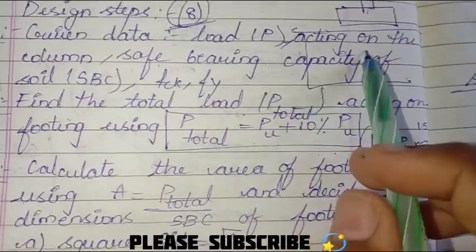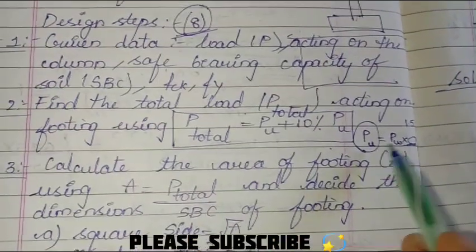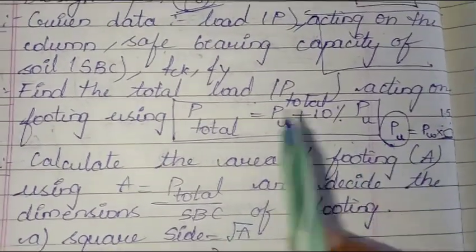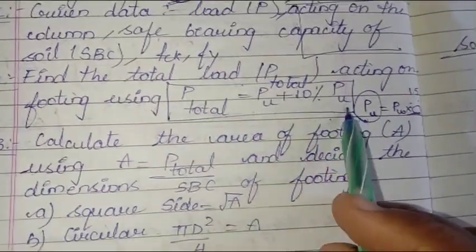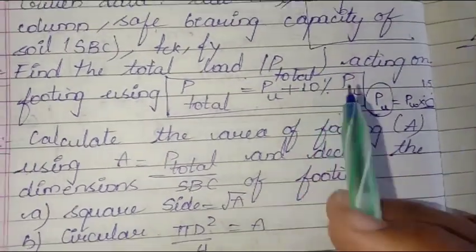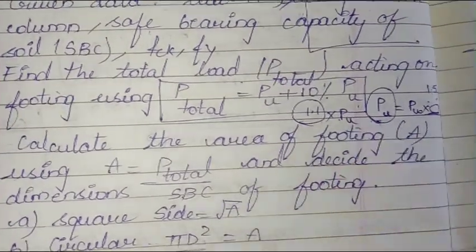We will be given the load acting on the column, that would be the working load. But when we need the ultimate one, we multiply the working load with some factor, that is 1.5. So once we get Pu, we substitute it in this: P total equals Pu plus 10% of Pu. Pu is the ultimate load taken plus 10% of that ultimate load, that is nothing but 1.1 times Pu.